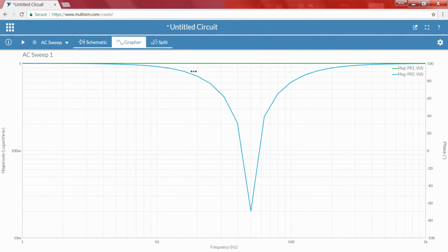So, when you see the valley, it is very narrow, that is why this is called a narrow band filter too. Very narrowly we can cut down one particular frequency. The reason is that we are looking to eliminate only the 50 hertz noise, and the other things we do not have to remove.